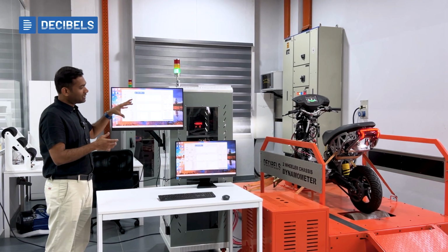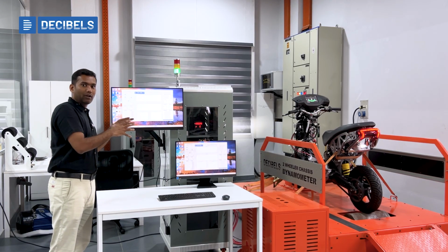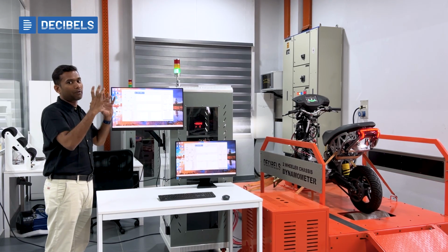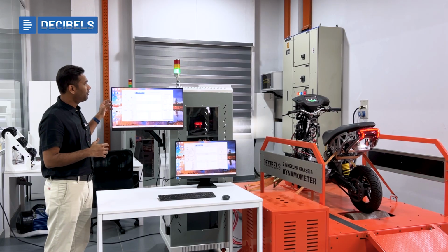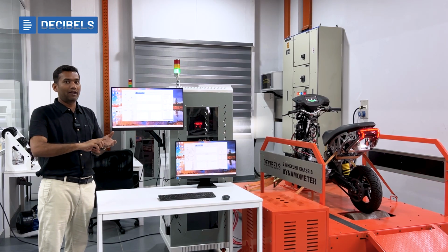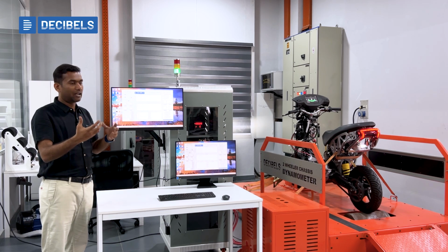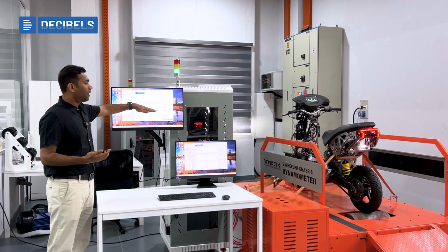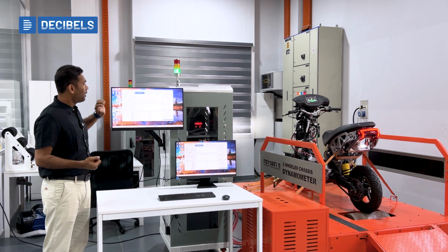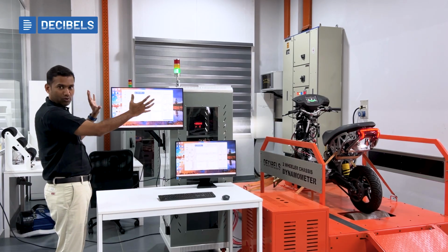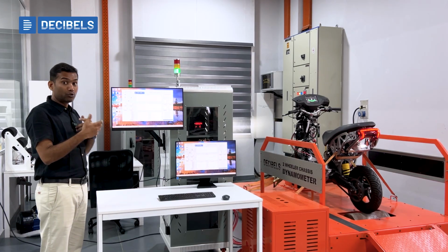The dyno, being a 4-quadrant dyno, has operation in all the possible quadrants. With the help of it, we can perform IDC drive cycle, MRDC drive cycle. We can even develop custom drive cycles and implement them as part of our premium software versions as well. This complete test suite also comes with closed loop controls as well.